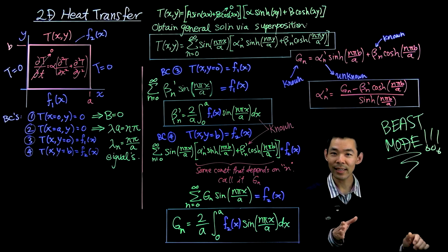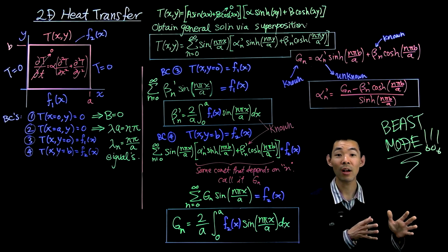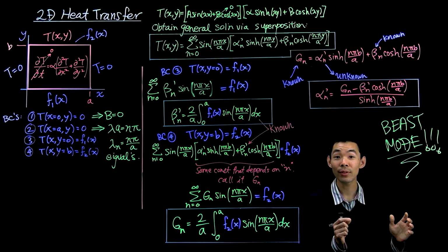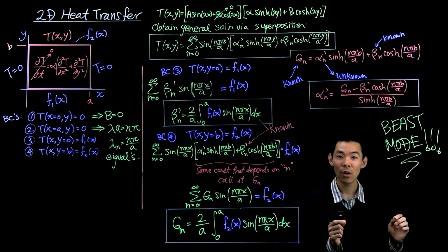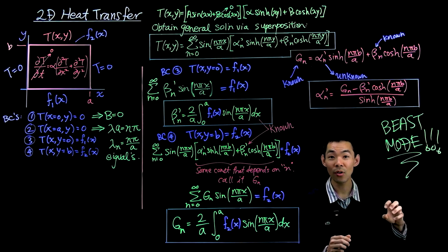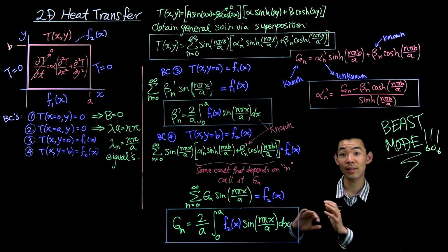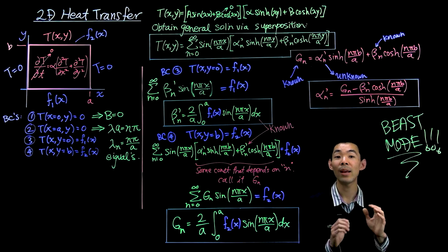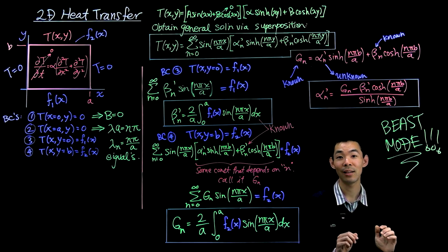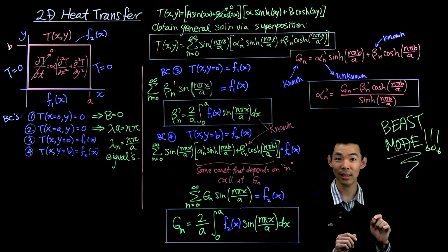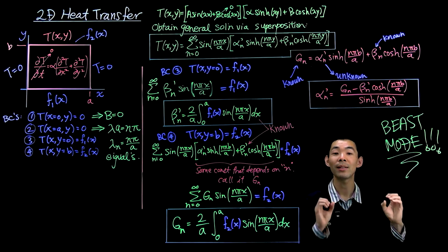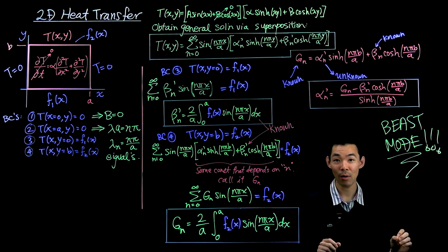Remember the transient 1D heat equation that we solved before, we were able to make that solution work when we moved the non-homogeneous boundary condition into the steady state part of the problem, and we had homogeneous boundary conditions to solve the transient heat solution problem, T transient, and that worked out fine. But we had zero boundary conditions to make that work.